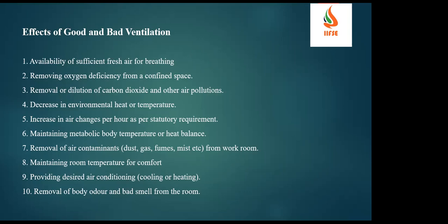Oxygen deficiency means less oxygen. Generally, the oxygen level will be 19.5 to 21%, which is a good range. Whenever the oxygen level falls below 19.5%, that specific circumstance is called an oxygen deficit atmosphere.